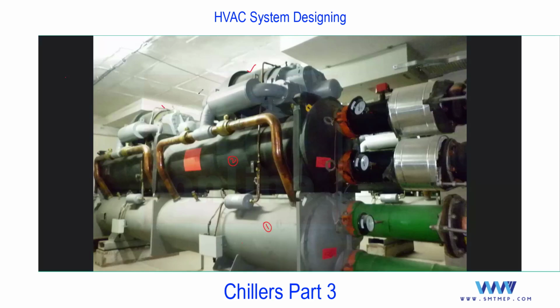And you'll find multiple compressors, and the expansion. So the same components: compressor, condenser, expansion, and the evaporator. But the condenser as well as the evaporator are both of the same shell and tube type. Now, can you identify which is the condenser and which is the evaporator in this image? Any guess?